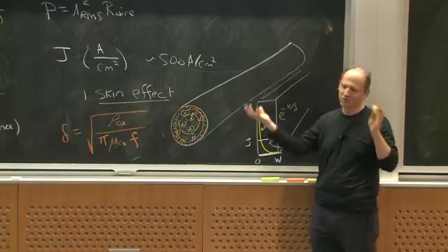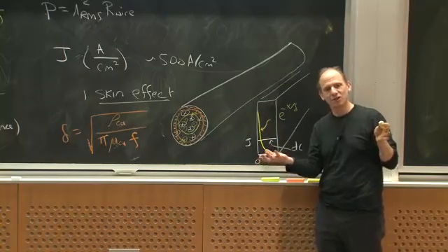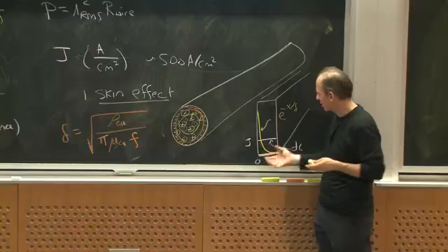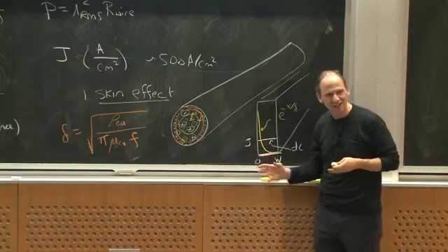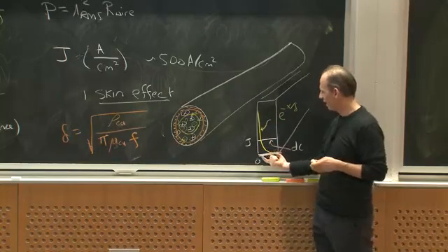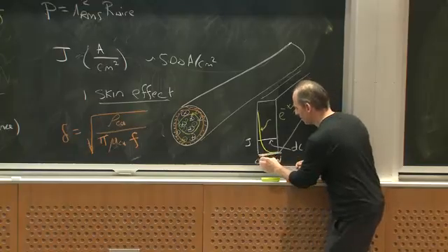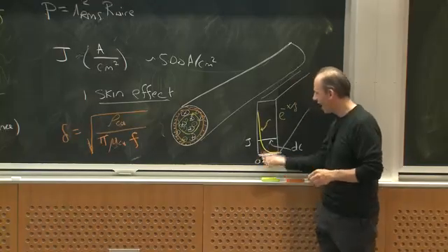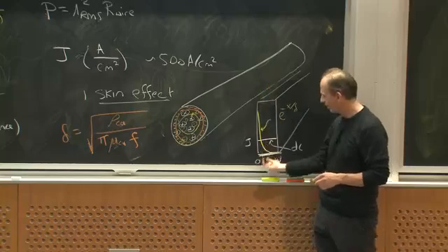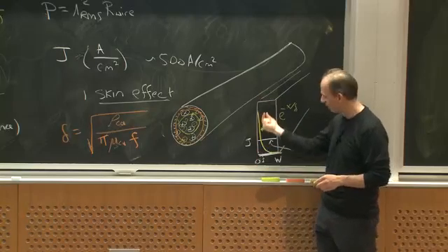It's just an interesting thing you can derive. So you can think about it from a cross-sectional area carrying capability. Even though I had W of width of wire, I can only use perhaps delta of it, and I can just calculate the AC resistance as if I had the skin depth.